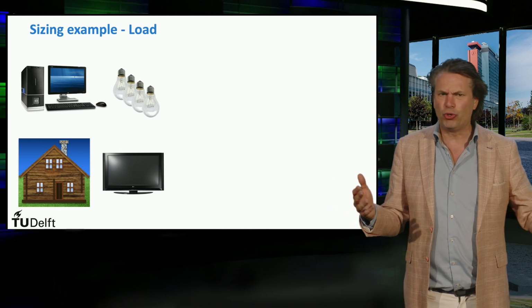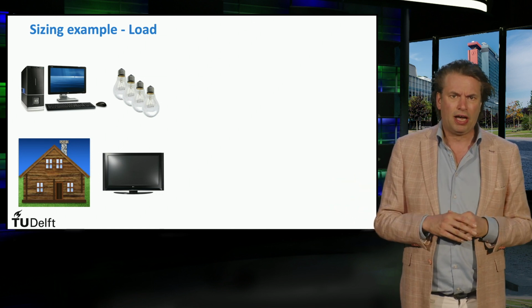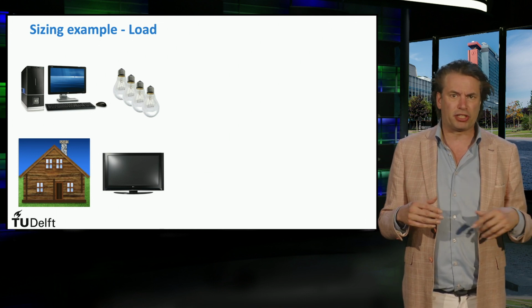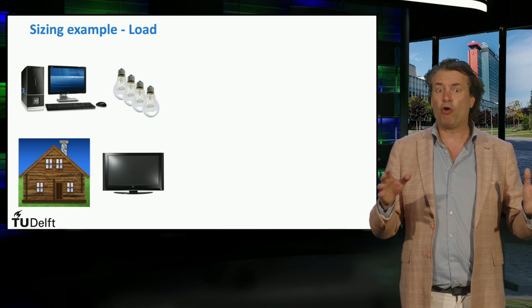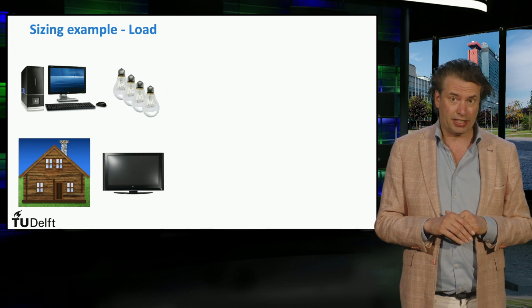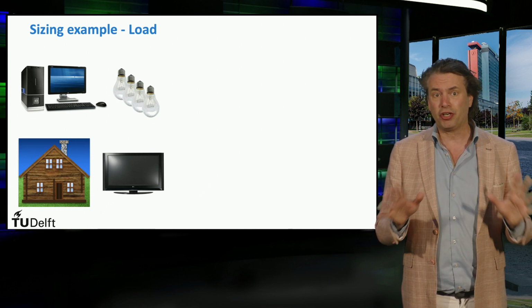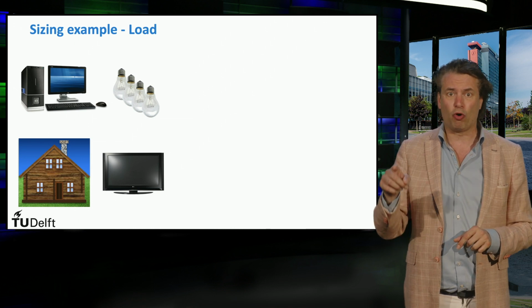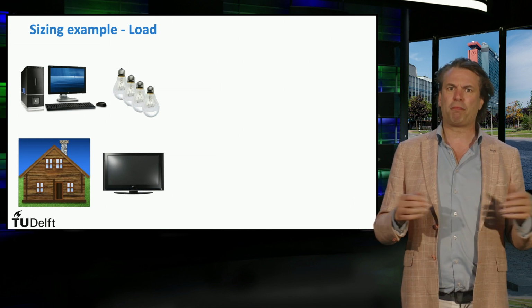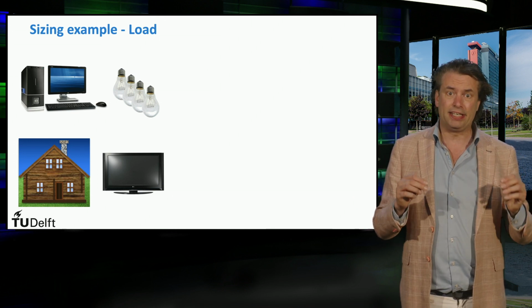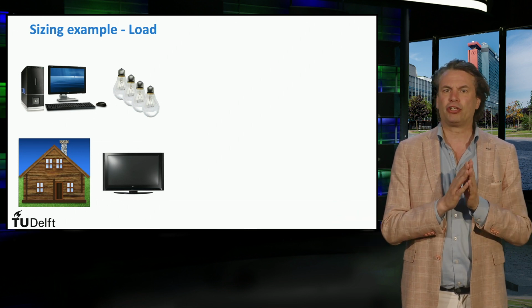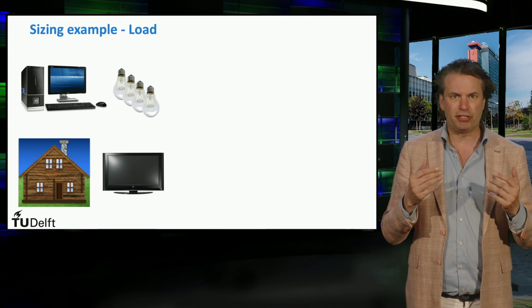These include the use of a simplified load profile, and disregarding the location's meteorological effects; ambient temperature and wind speed are ignored. Moreover, for the simplified design, we simply use the standard test conditions data of the PV modules and therefore do not take into account the sun position or PV module orientation. In this video, you are going to learn about the different steps involved in this design strategy. Let's begin. This method follows a 6-step plan to complete a PV system design.